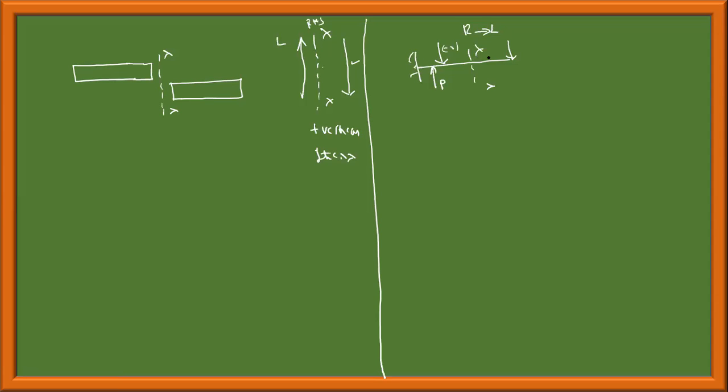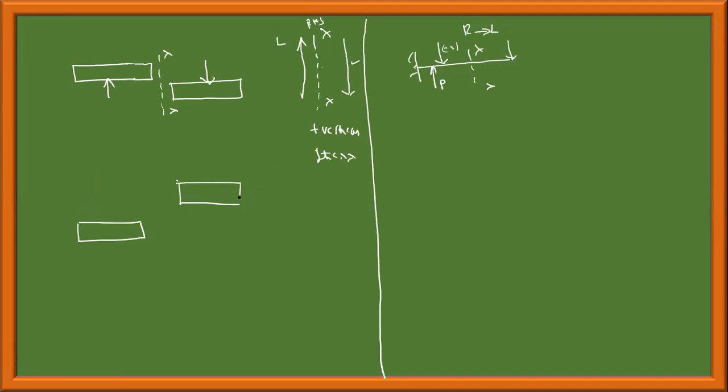It will come from any one side. Okay, now negative shear force. If I apply a load like this, it will go like this, will come like this. Okay, negative shear force. This is opposite to that. This is my section. In this case, this is negative. My section is towards the right hand side. Load is acting downwards when I come from left to right, and if I come from right to left, the load is acting upwards and the section is towards left hand side, this is your negative shear force.